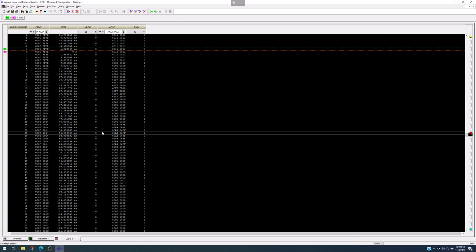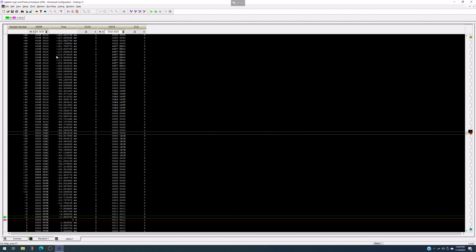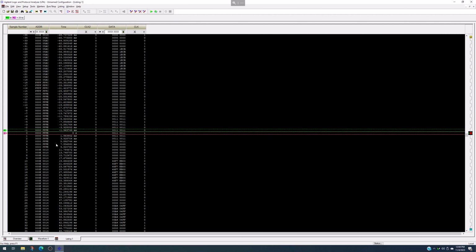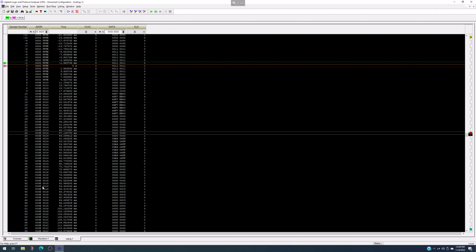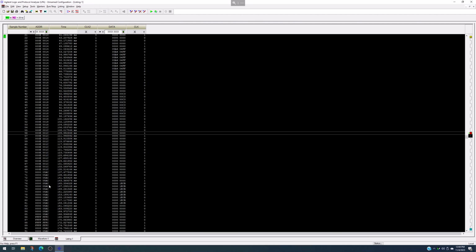So I can see that it captured information before the trigger and after the trigger. But from the trigger on, I can see it's going from address E10 to E14 to E18. Here I can see it's over looking at my RAM at 5AC, and I can see that the current counter stored in there is 1ECB, and I can just follow through. Now, I know these values because I've looked at the code. I know the simple assembly code I wrote and what addresses it's at in ROM, so I recognize this. Now I could go over to my assembler and look at its listing output, and it'll show me what it's doing at each address. And I could use that to decipher this. I just happen to know this one is so simple that every time I see 5AC, that's this counter.